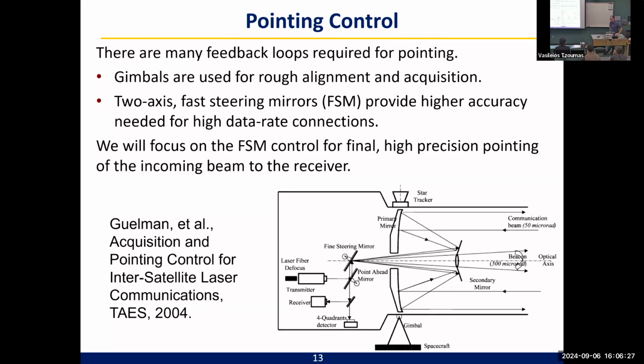Depends on what you mean by a certain kind of preference in the noise. Some specific mechanical system will provide noise in a certain kind of form. Roughly speaking, I would think of these as lightly damped second order systems. And then you're going to see there's lots of high frequency, flexible structural mode type stuff. So to some degree, they can cancel all the noise up to a certain bandwidth, and then beyond that, it's just outside the bandwidth. I don't think there's a preference in the low frequency range for the noise properties.